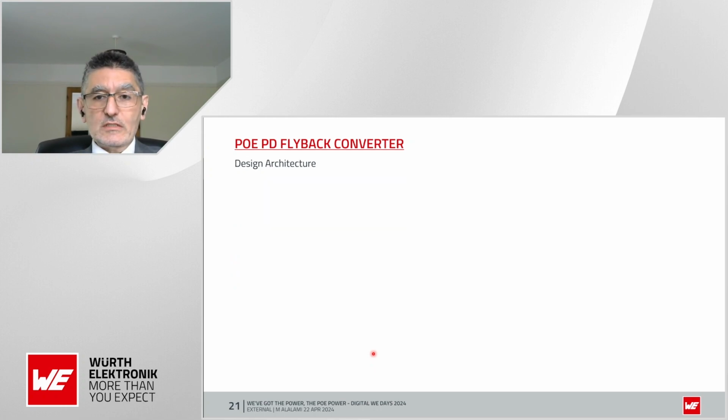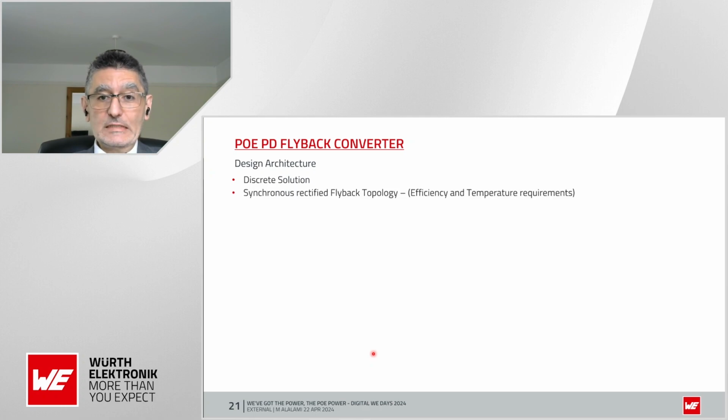So the design architecture, as we started putting the solution together: I've decided to go for the discrete solution, one of the three options we mentioned at the beginning. So we'll go for two different ICs. I've also decided to go for a synchronous rectified flyback topology, and that's to maintain the efficiency on the output side, given the 5 amps of current, and also for temperature requirements as well.